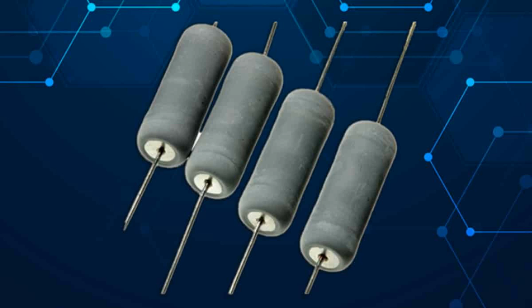Melting or opening. As the heat builds up in the conductive element, it eventually reaches a critical temperature. At this point, the fuse's design is such that the conductive element melts or opens, creating an air gap in the circuit. This deliberate interruption of the circuit disconnects the power source from the load, effectively cutting off the current flow.